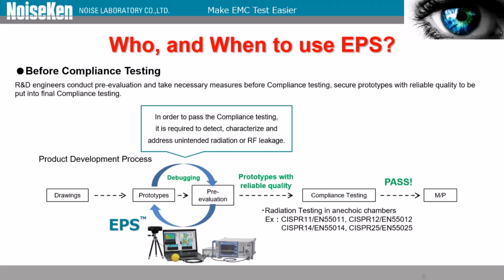And who and why, when to use the EPS? Well, the first case I would like to say is before the compliance testing. In order to pass the compliance testing, it is required to detect, characterize, and address unintended radiation or RF leakage. So the R&D engineers conduct pre-evaluation and take necessary measures before compliance testing, secure prototypes with reliable quality to be put into final compliance testing,